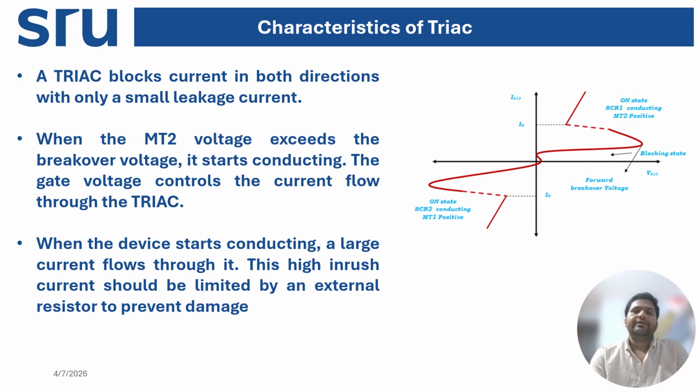However, in a practical circuit, we don't really rely on breakover voltage. Instead, we use the gate terminal to trigger the conduction at lower voltage.